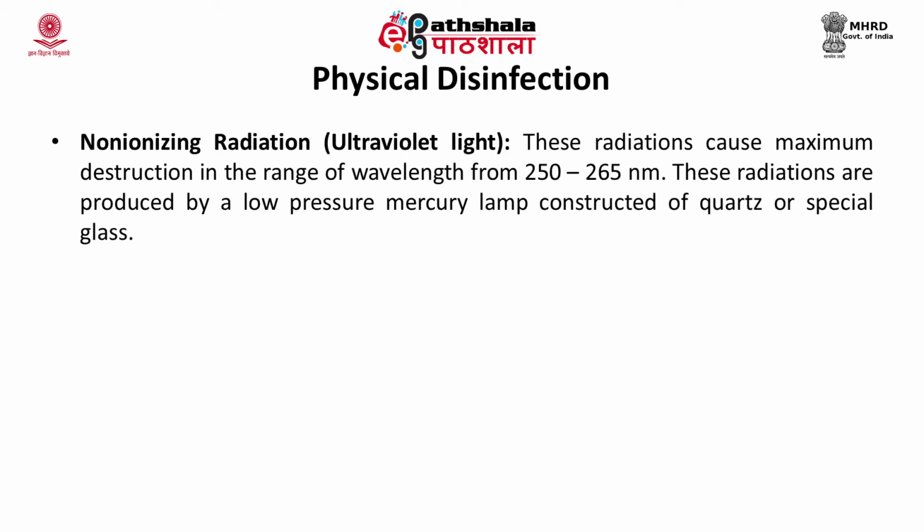Non-ionizing radiations that include ultraviolet light cause maximum destruction in the wavelength range from 250 to 265 nanometer. These radiations are produced by a low pressure mercury lamp constructed of quartz or a special glass.